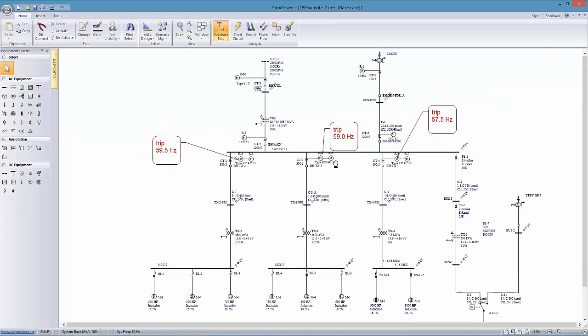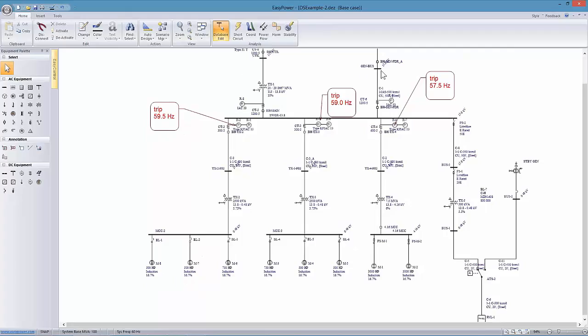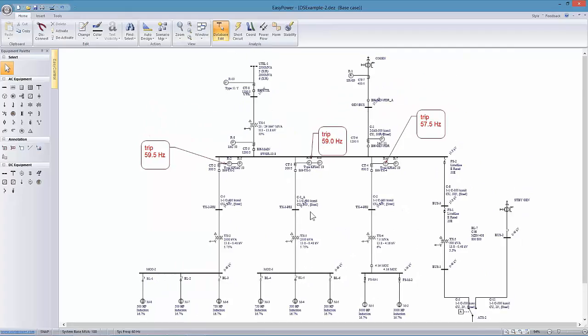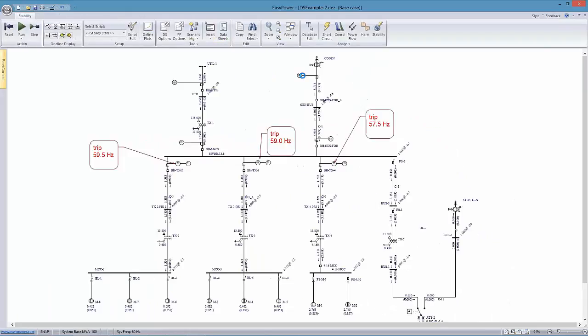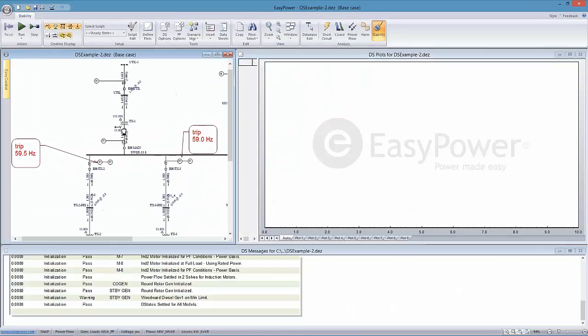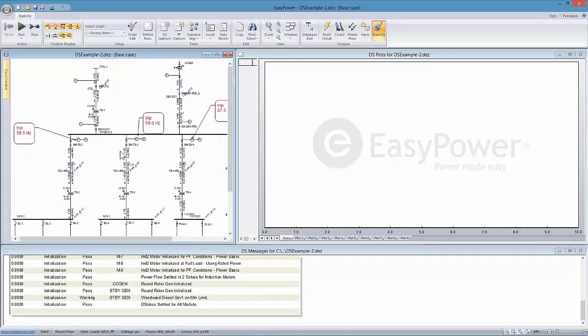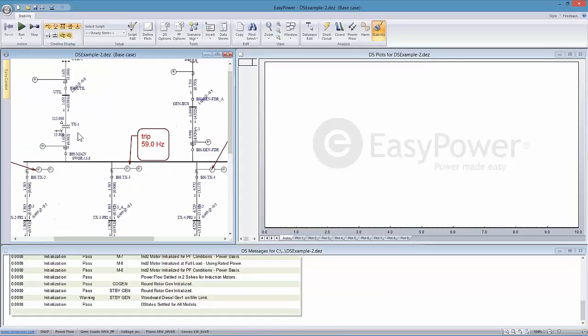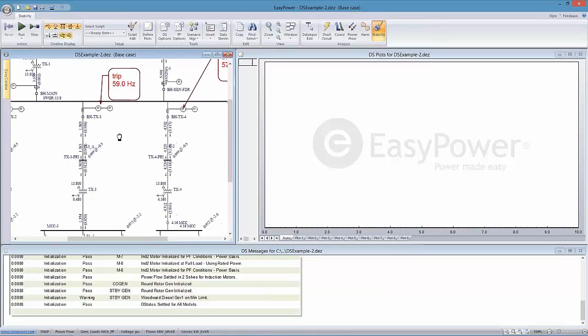So ideally, if we pull the plug on the utility, we would like to see the response of the cogeneration pick up the loads, so we lose a minimum amount of our total system load. So we go into stability focus, and you notice we have the 3 frames. Again, on the left is the one-line diagram that has already an existing PowerFlow solution, and this is resolved, showing us what the typical display for a load flow or a PowerFlow study would be.